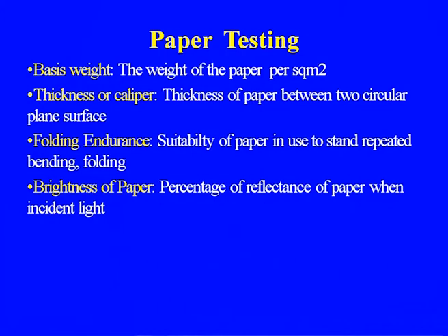If their requirement is 60 GSM and the uniformity of the GSM is not there, definitely they will be losing in terms of total weight tonnage. Normally writing paper is around 50 to 60 GSM, tissue paper is below 30, board paper may be 300, 400 GSM.